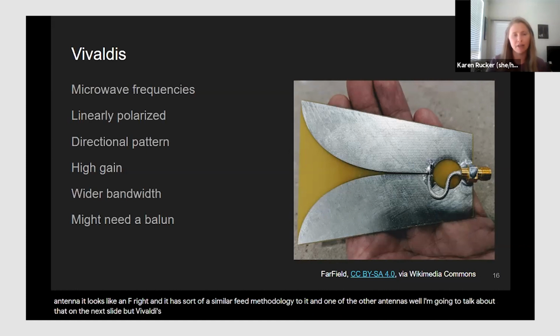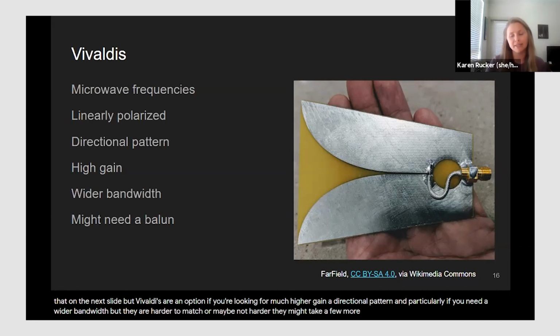But Vivaldis are an option if you're looking for much higher gain, a directional pattern, and particularly if you need a wider bandwidth, but they are harder to match, or maybe not harder, they might take a few more steps to match than a simple patch, right?